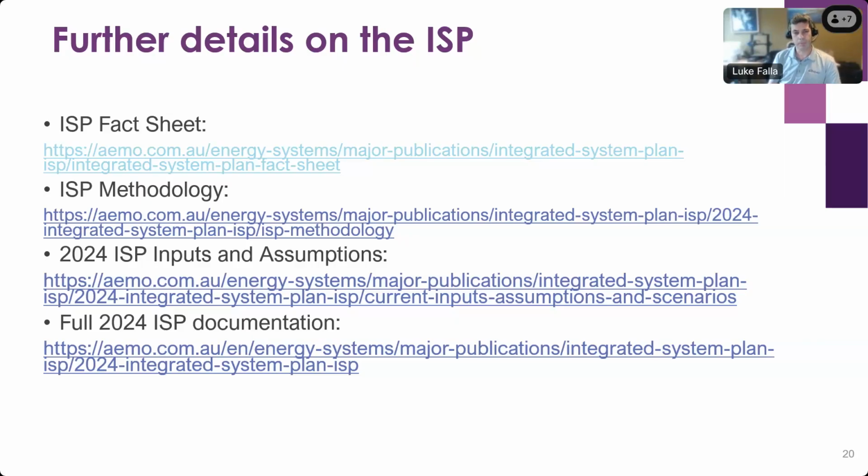So yeah, we don't have a system which would just get any load flow and run automatically. We do tend to look for specific conditions, the peak load conditions, the high interconnector flow conditions, the maximum VRE conditions, and we look over those times. So we look at times when we think the network upgrade is going to occur, and we'll extract snapshots for purposes like that. Items such as where we look at system strength or other security services can be a bit easier, where they don't need to solve load flow, they just need a network impedance in the background. And we can iterate over those quite quickly, and we do scans, and we can build load duration curves from the results using those methods.